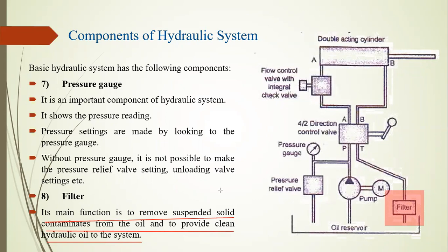It is required in every hydraulic circuit to clean the oil and remove the solid content from the oil. We can attach it in different places, like here, before the pump and hydraulic motor. Otherwise, we can attach it here after the pump and motor set. Otherwise, lastly, we can attach it at the end of the reservoir tank. The filter is an essential part to add in a whole hydraulic system to clean the hydraulic oil. Okay. Thank you.